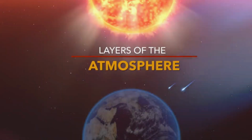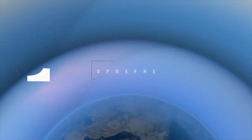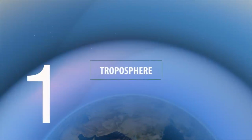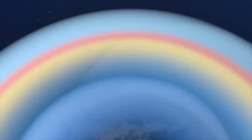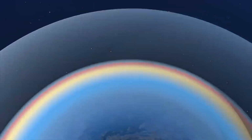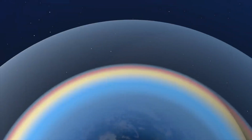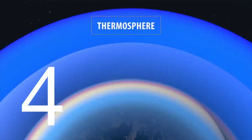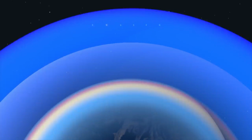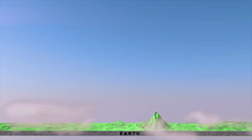Layers of the atmosphere. There are several layers to the atmosphere, with the troposphere being closest to the Earth's surface, extending to about 60,000 feet at the equator. Following is the stratosphere, mesosphere, ionosphere, thermosphere, and finally the exosphere. The tropopause is the thin layer between the troposphere and the stratosphere. It varies in both thickness and altitude, but is generally defined where the standard lapse, generally accepted at 2 degrees Celsius per 1,000 feet, decreases significantly, usually down to 1 degree Celsius or less.